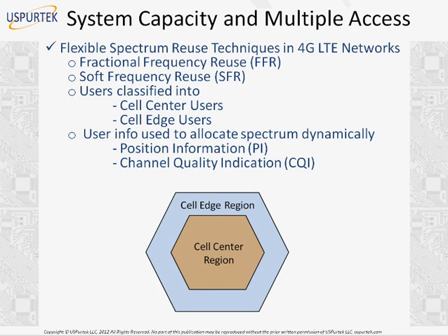Okay, there's a question: near far effect, right? Well, no, this is not the near far effect we discussed earlier. This is definitely in the far field, because we don't do wireless communication within the near field. Near field we use only for measurements in one scenario which I described earlier, just to do antenna measurements. This is not used for digital communication. Any mobile user must be outside the near field. Okay, so this is entirely different. Here it's only based on signal strength, signal to interference and noise ratio (SINR), which determines the boundary of the cell center region and the cell edge region, that is, where the signal falls below the threshold where the users cannot get acceptable quality.